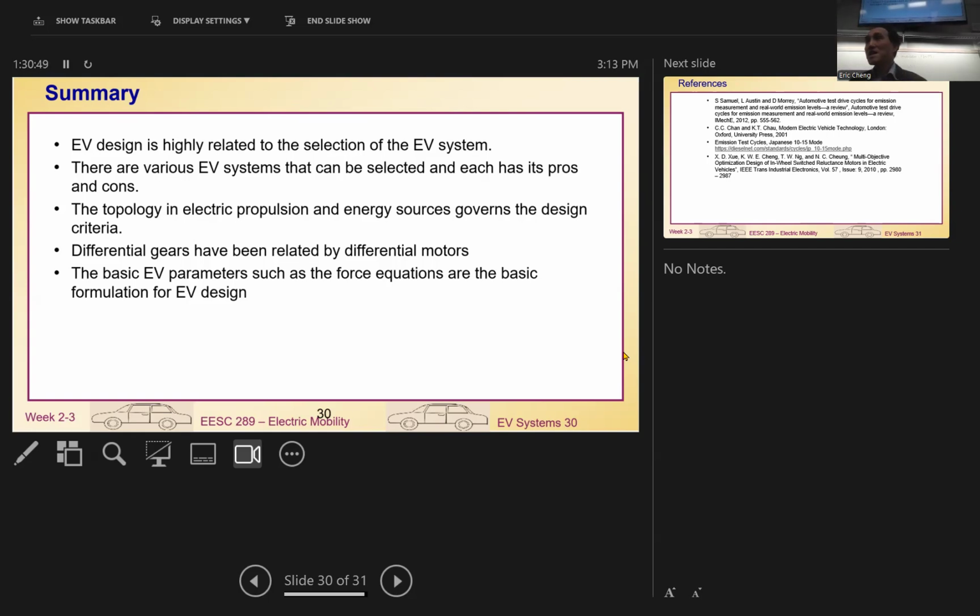And then once you decide that, another question will be how to handle the interference from your motor. For some motors, we use IGBT, then we have pulse width modulation that generates a lot of high frequency pulses, like 20 kilohertz, 600 kilohertz. That's the thing happening around the whole vehicle. The power components, the high current, all the high frequency appear in the whole vehicle. How are we going to design the DC bus to eliminate all this noise? The noise is another big problem, because we are not using pure DC current to drive the motors, it's a pulsating current, so that causes a lot of noise.